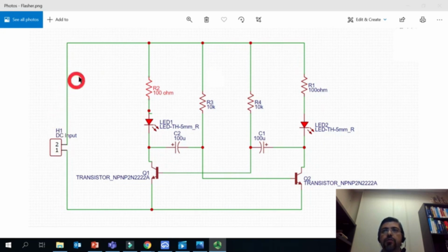So usually if you want to make the PCB board of the circuit or any other circuit, so you need to first implement this circuit on the breadboard and make sure your circuit is right, the diagram or schematic that you have is right, and whenever you make sure that's right, you actually move to the next step, which is to design a PCB board in your software. For our case, that will be designed in the EasyEDA.